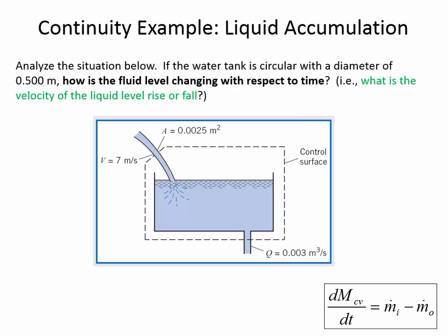And so here, the way that continuity is satisfied, remember we know that in has to equal out, so you can't have the cross-sectional area be the same here where the water velocity is slow compared to here where the water velocity is fast. As it speeds up, it contracts in diameter because the flow rate needs to remain the same. Q has to be the same, and remember Q equals VA. So the flow rate Q is the same here at the top of this stream as it is just before it comes into the tank. The Q is the same, and so if the velocity increases due to gravity, then the cross-sectional area has to decrease, and that's why the diameter is narrowing.